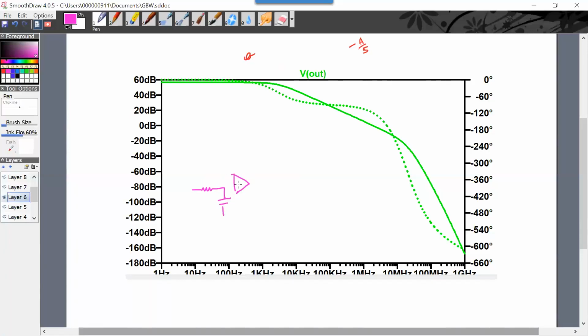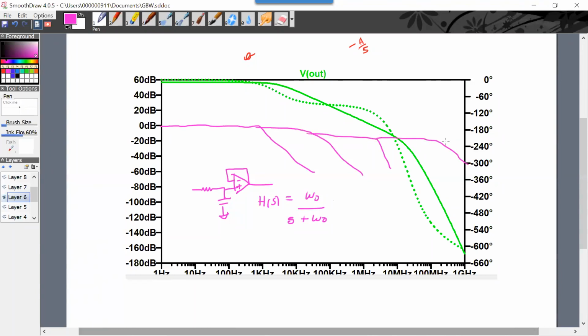You might see a question like this. If that op amp is ideal, we have something like that, right? And there is no gain because of that buffer. So I can have a low pass filter and I can have a cutoff there. I can have cutoff here, still work, cutoff here, it'll still work. But if I try to have my cutoff frequency out here beyond that limit, well, no, that's not going to work, all right?